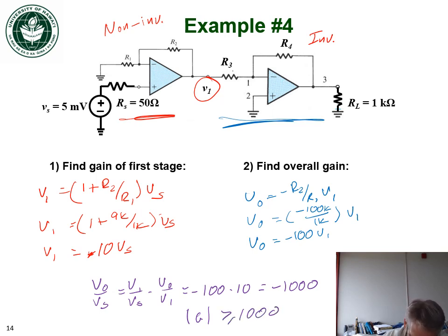And we didn't even have to use the largest resistors. We chose a 9K for R2 here instead of the largest possible resistor to make this a little cheaper if we're actually going to fabricate something like it.